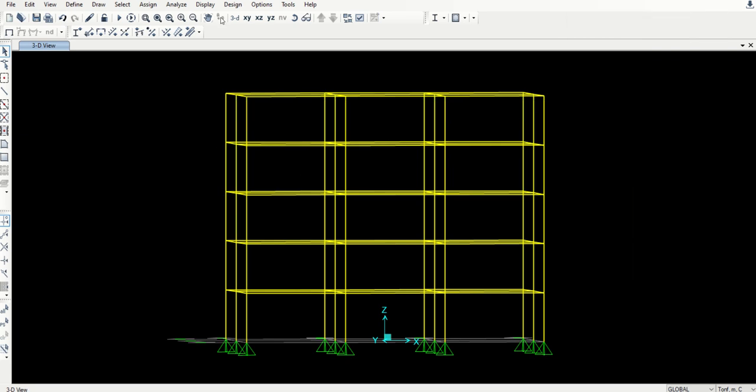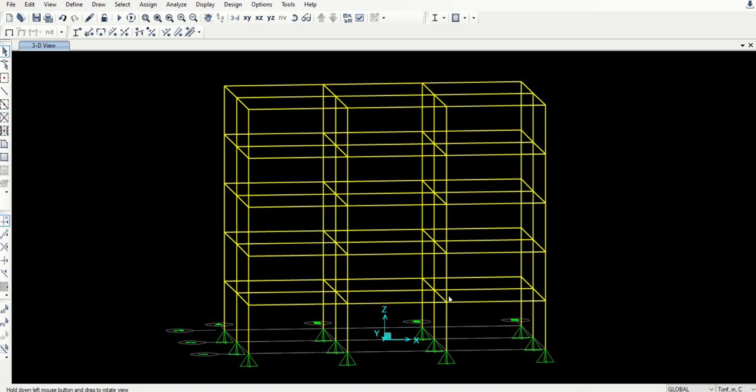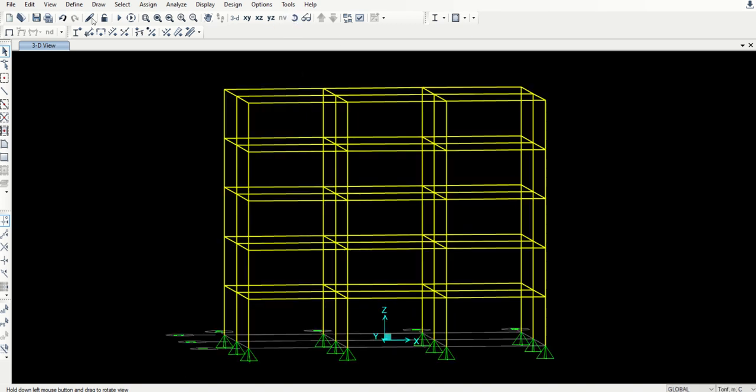Okay, now as we have groups, we need to create section cuts. Okay, what is a section cut? A section cut is a way that allows you to integrate an amount of loads among the nodes that you select. Okay, you can select something, or you can create groups.